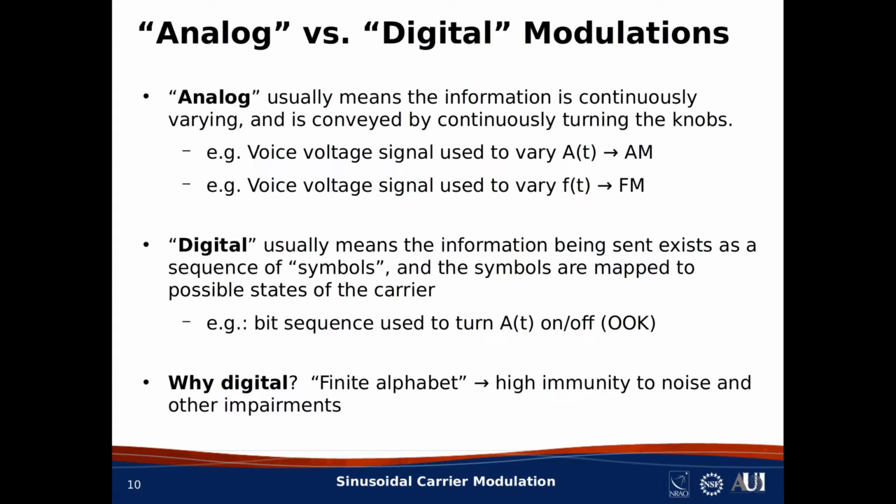Using one of these error control schemes, we can get back to the condition that nearly all of the bits will be correct, even when the signal is received in very low signal-noise ratios, where many of the initial decisions might be wrong. This is where the finite alphabet property of digital modulation really pays off. There is simply no analogous form of error correction for analog modulation, so this accounts for much of the preference for digital communications in modern radio systems.